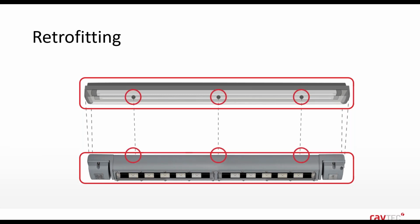Fixing centres, so the luminaire should have the same fixing centres as the existing fluorescent too. These are located in the same position and have the same thread and the same depth as the fluorescent fitting, and the same brackets can be used too. And utilising the same brackets on a job could save you quite a lot of money during the installation.